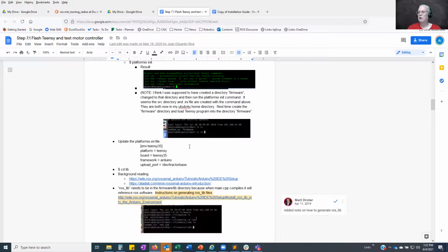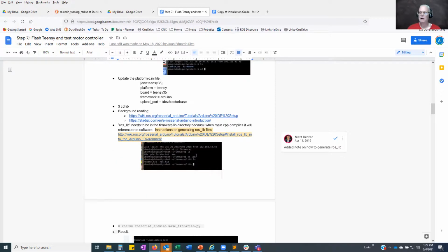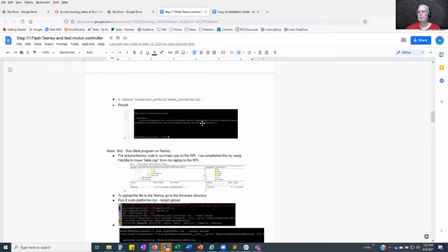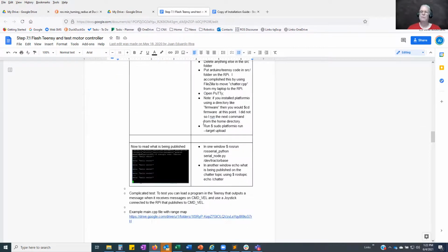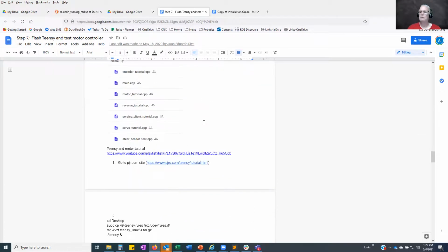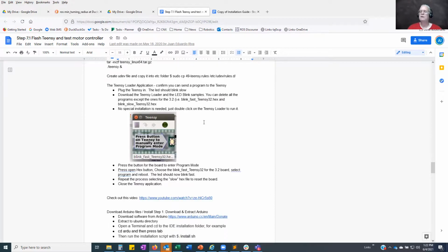So on the Raspberry Pi, what I did was I just went to physical USB port static port naming. So I said the first port I'm going to call GPS and the second port I'm going to call laser scanner or whatever. I just went down the line, and I didn't have any way to identify the different modules. So it says if it's plugged into this USB port, it's going to be this type of device.